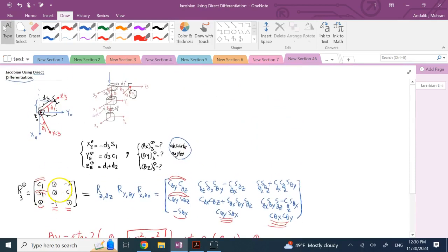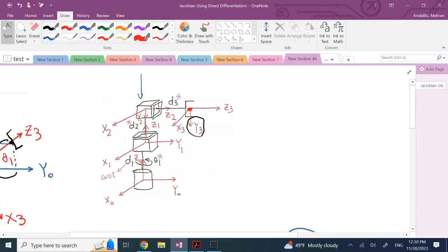Will that do the work? Yes. If you look here, if I rotate about the x-axis, about this guy, I rotate negative 90 degrees. That's the positive direction, and since it's negative, I should go in this direction and go 90 degrees. If I do that, what will happen to frame 0? Well, x is going to stay like that, but y is going to go down and z is going to go this way. So this is going to be z of the intermediate, this is going to be y of the intermediate, and this is going to be x of the intermediate. Then what?